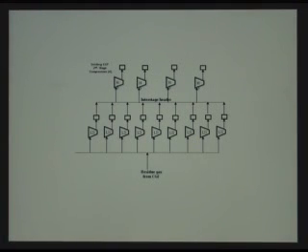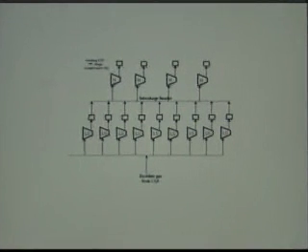And so this is the CCP up at Prudhoe Bay. Currently it has 9 low-stage compressors all operating in parallel, feeding to a common interstage header, feeding 4 high-stage compressors. And this is doing gas reinjection. All the residual gas that's coming out of the facility, out of Prudhoe Bay, if it's not being used for process or for fuel gas, it's got to get put back down inside the well, inside the formation. So these machines, amongst others, do that.